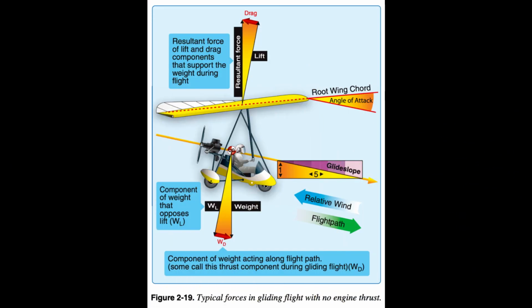Weight. Weight is a measure of the force of gravity acting upon the mass of the WSC aircraft. Weight consists of everything directly associated with the WSC aircraft in flight, the combined load of the total WSC aircraft, wing, wires, engine, carriage, fuel, oil, people, clothing, helmets, baggage, charts, books, checklists, pencils, handheld global positioning system (GPS), spare clothes, suitcase, etc. During gliding flight, weight is broken down into two components: the component that opposes the lift, acting perpendicular to the flight/glide path, and the component that opposes the drag and acts in the direction of the flight/glide path.